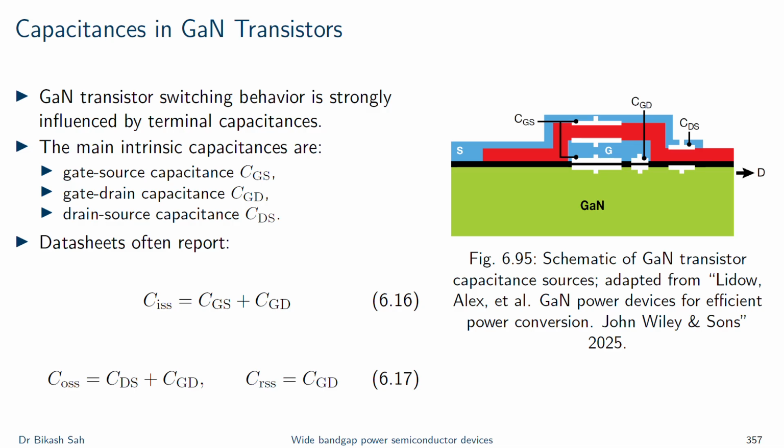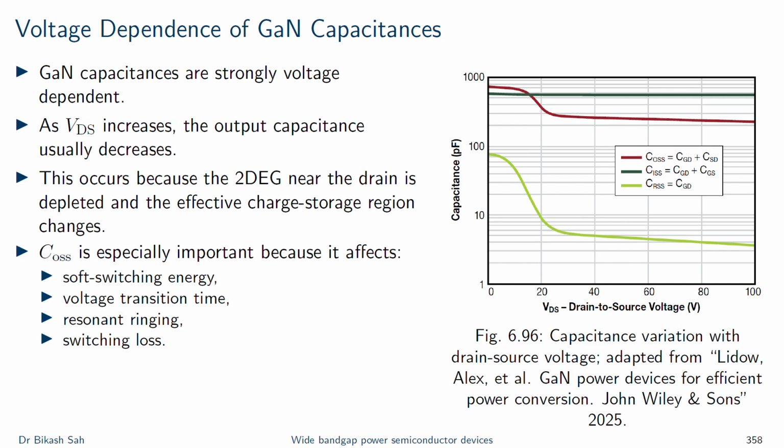So in GaN, capacitances are often small, which enables fast switching, but their small value also means that parasitic capacitance and layout capacitance become comparatively important. A few picofarads of unintended coupling can influence switching behavior. Therefore, capacitance is not just a datasheet number, but also, I would say, very important for the entire converter electromagnetic design, especially when we go into soft switching power converters. I would say this becomes more and more increasingly relevant.